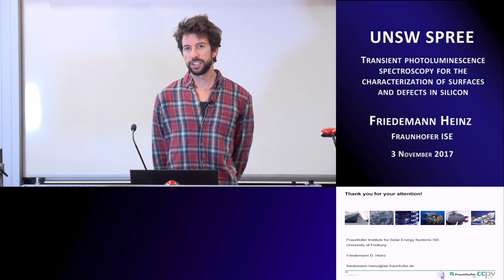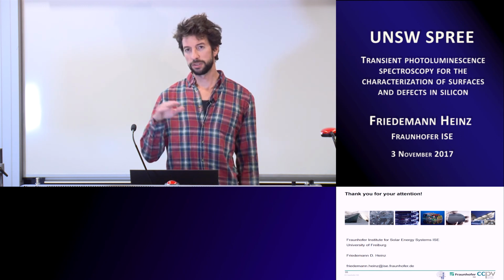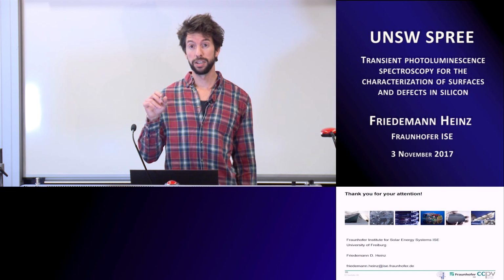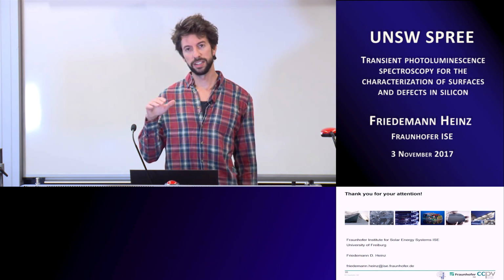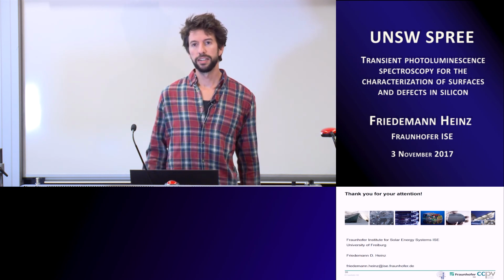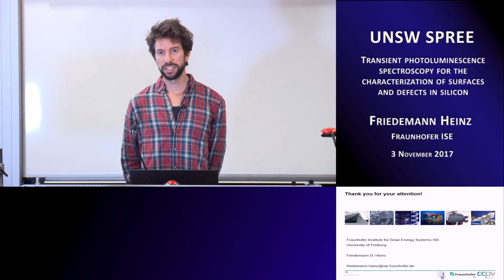So the first approaches led to trap depths where one was quite central in the band gap, I think 0.48 electron volts, and the other 0.7 eV from the conduction band. But that was when I didn't look at this multiple trapping mechanism, so this could change some things.